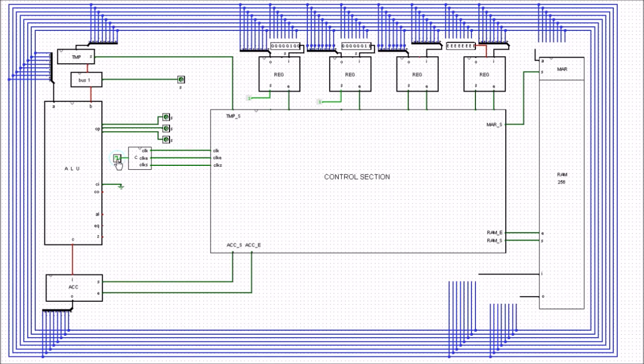Right, okay. Now on the 12th clock pulse, you'll see now that what's happened is we've taken this value 1, 1. You can see the enable has gone high in this register R0, and it's placed that value onto the bus. So the least significant bit and the next significant bit have both gone high, and you can see that in the control section.